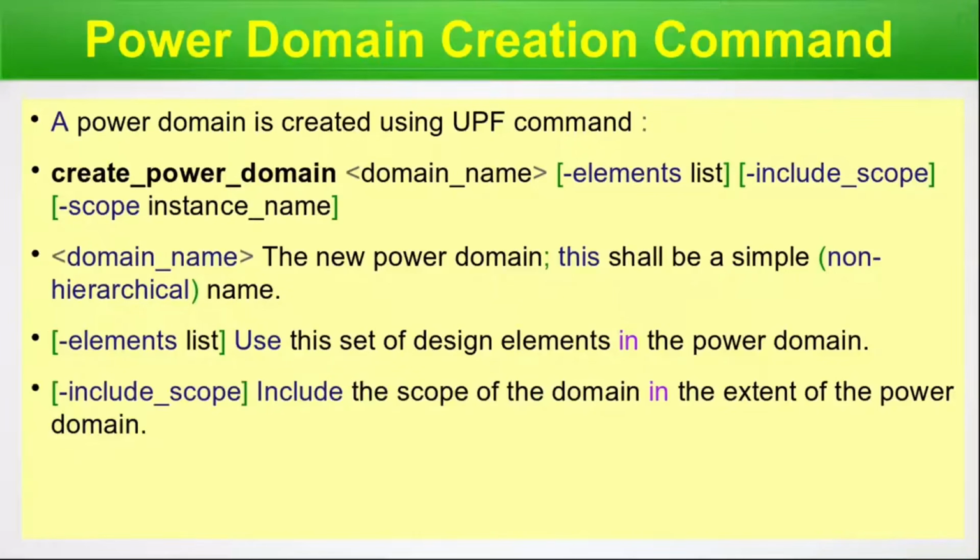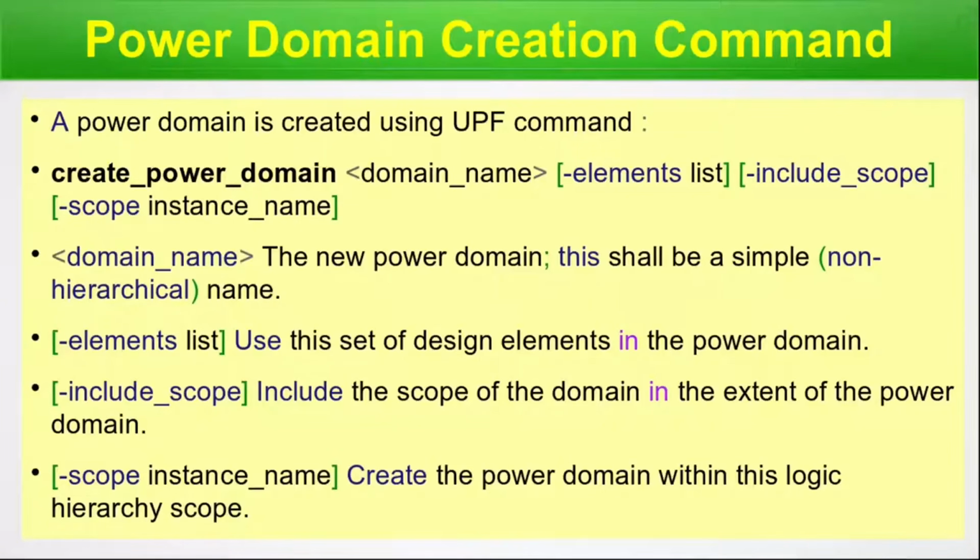Include scope: we include the scope of the domain in the extent of the power domain. And finally, scope with the instance name: create the power domain within this logic hierarchy scope. So include means we include the existing scope, and here scope means we create our domain within the hierarchy of the scope. So better you understand this with an example. Let's move on.